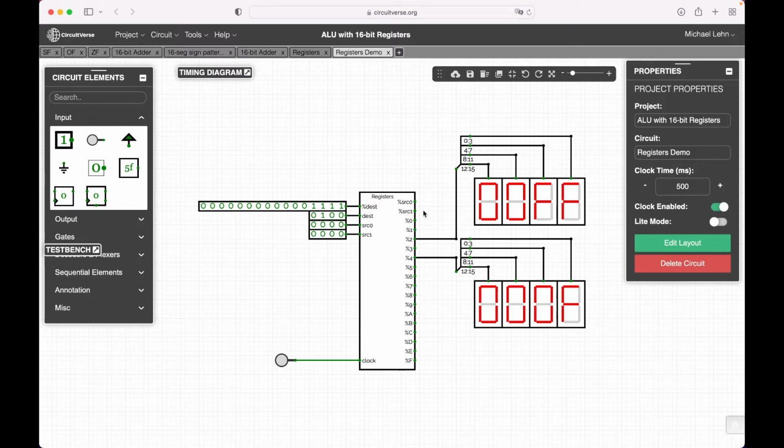But usually I will not only use the registers for storing data, but also for using them as an operand for an operation. For example, I want to add register 2 with register 4 and then store the result in register 6, for example. And so I just need 2 of these registers as an operand. And for getting an operand, I use, for example, here this source 0 or source 1.